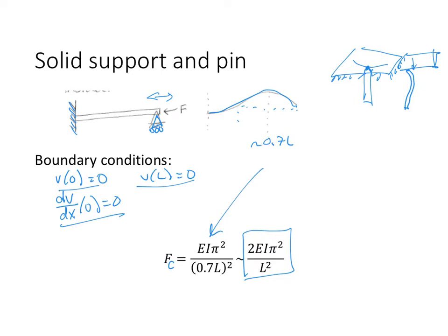So at this point, we have defined the Euler buckling force for 4 types of columns. The way we know which of these Euler buckling force formulas to use is by asking how the situation you are given affects the boundary conditions. Rarely in real life situations do we have something that's really clearly a solid support or a pin or a hinge, but we can usually logic from the information we know as to whether it's allowing rotation and lateral movement.